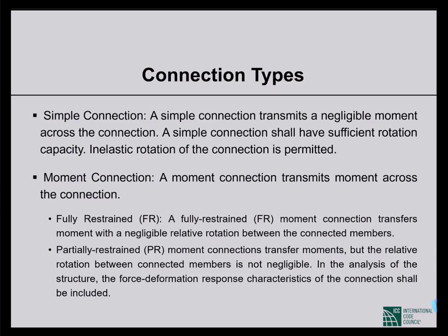And in case of partially restrained connections, the connection details are such that they can partially transfer the moment from one member to another, but at the same time, they have some amount of relative rotation between beams and columns. So the connection itself goes under some rotation, and at the same time, it also transfers some amount of moment.